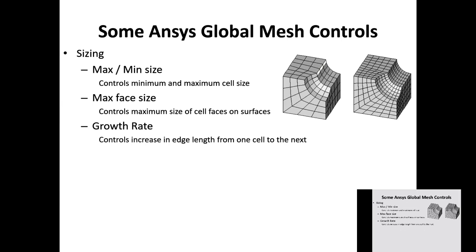For example, for the walls, you need a boundary layer. For the inlet and exit, you need a good resolution, so that it will pick up the inlet or exit velocity profile properly. Therefore, you need to control the mesh on the surfaces first, and then